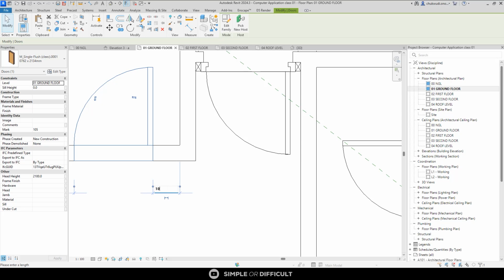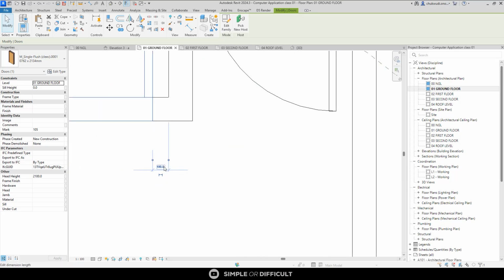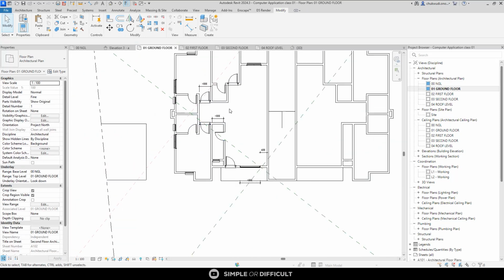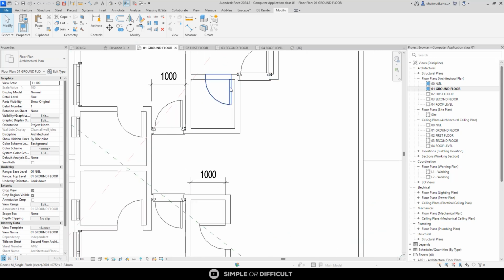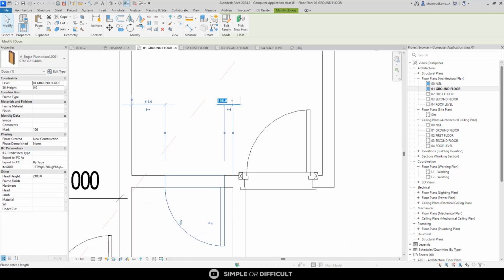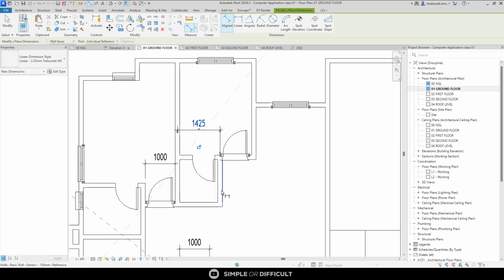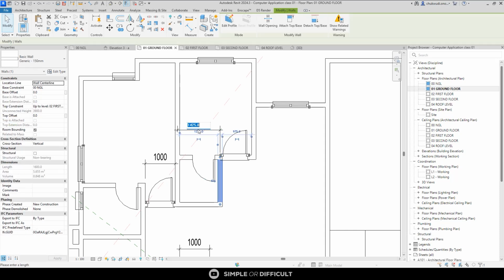So here I'm going to make sure that we have like 100 mm from that wall. Okay, let me just say 150. No, 100 mm is okay. For architrave purposes, if you're going to have architrave, you have to have an allowance like that so that I can be able to put your architrave. So the same thing over here, 100 mm.